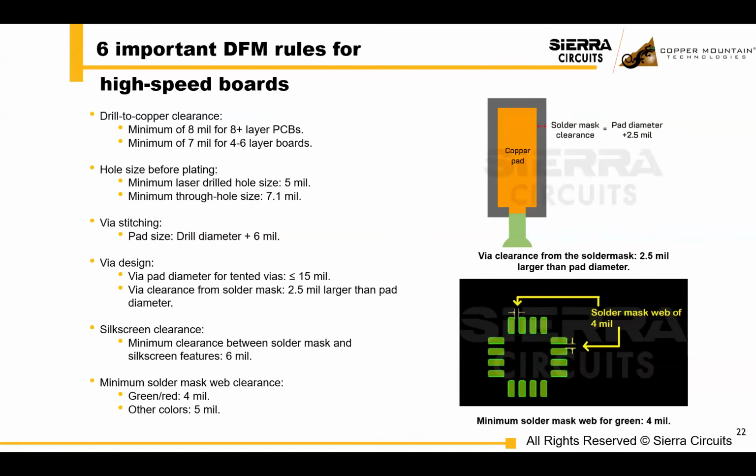If you have a 20 layer board with sublams, the more drill to copper you have, the better. A lot of people will do a sublam and then have a through via through the two subs. If the drill to copper is not good, then some fabricators will not be able to build that construction. So drill to copper is a really key thing, and design tools don't check for those in the DRC. So it's important to ask your fabricator if they can do that.